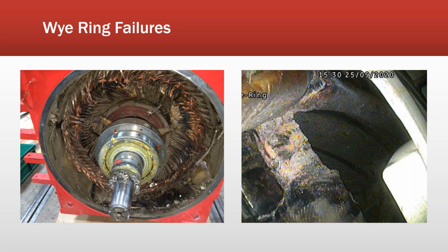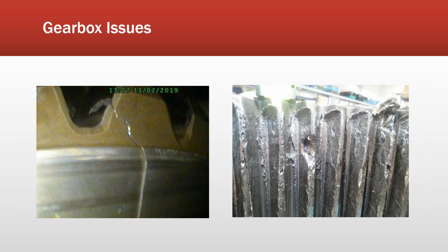So normally we'll see a separation of insulation. This one here is, I believe, a Suzlon. Suzlon also used to do a little bridge across these to try to get them to run longer. We run into that fairly often. I'll get into some of the false positives as we go through it. But in any case, that's normally what something may look like. Of course, gearbox issues, we found a few extremes. This is smeared planetary gear.